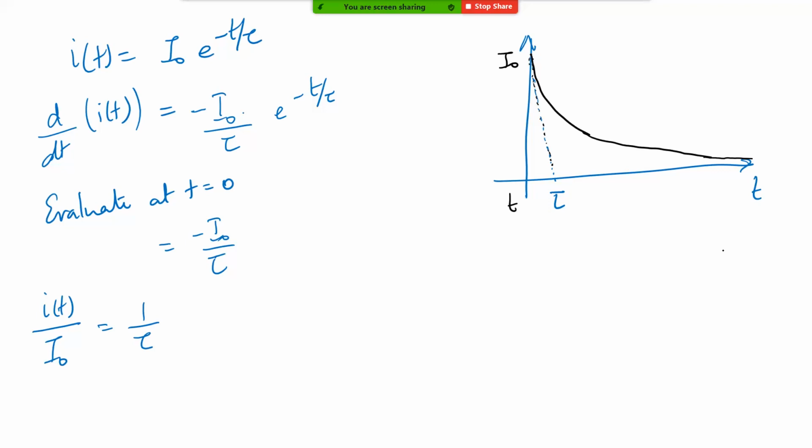When the capacitor is charging or discharging, the current waveform will look something like this. Let's suppose you have an inverter connected to the supply. The supply current will look like this. The polarity is in the opposite direction because for a voltage supply, current flowing out is taken as negative and flowing in is taken as positive.